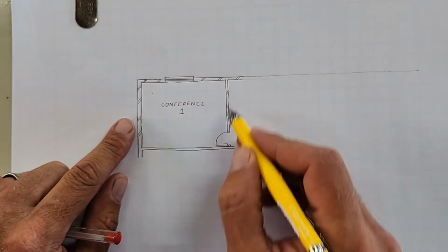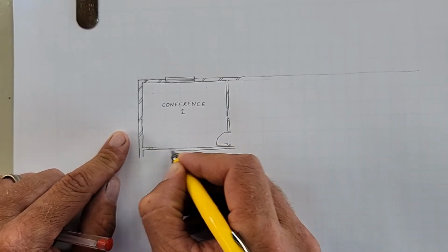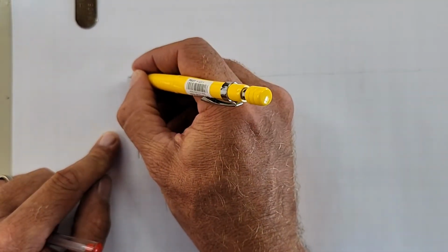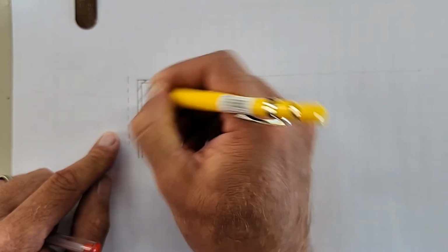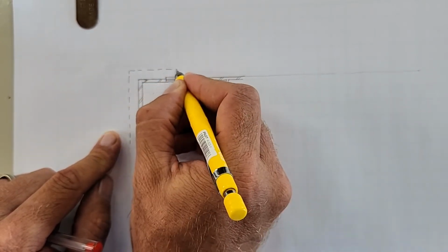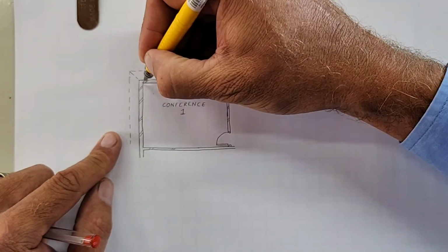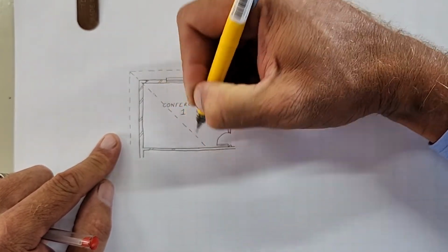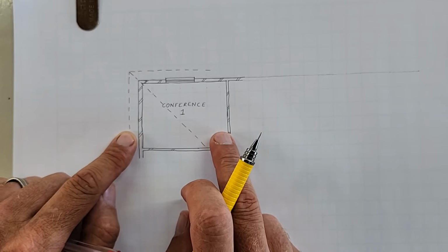So, in this conference center, we've got our window. We have our internal and external walls. There's the hatching. We've got our door. It's labeled. The one thing that's missing here is the roof overhang. So, you're going to have to show us your actual roof overhang on this drawing. Okay, and of course this one will have a ridge. Okay, do I have to show electrical fittings here? No. All right, this is one of the conference rooms, but it's going to be at least this.